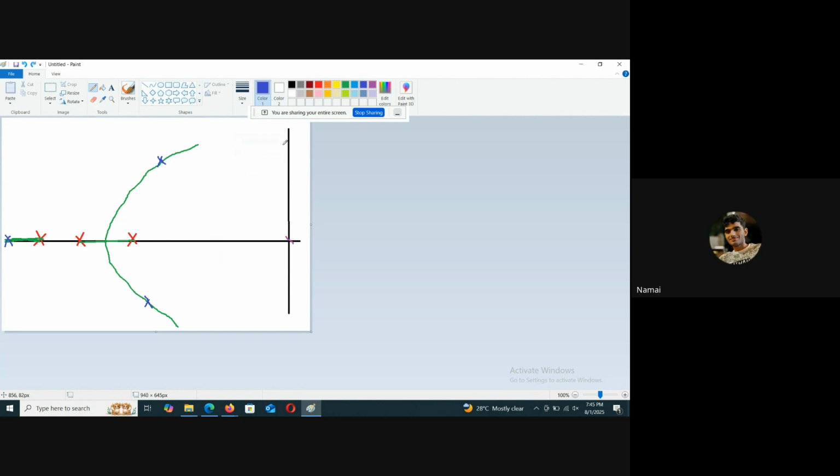So what you do is you place a pole very close to the origin compared to the others, and also place a zero that is farther, with ratio beta, but these two are still much closer to the origin. From the point of view of this faraway region, this is basically an approximate pole zero cancellation. If you see from very far away, two close enough points will appear as one, right?